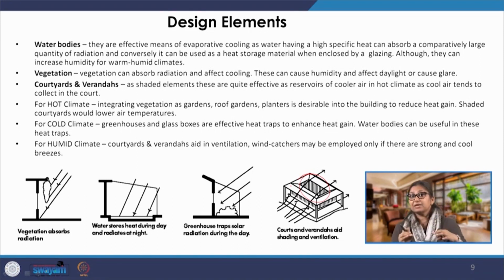That night ventilation will take away the heat, the walls and surfaces of the building will be cooled through the cool air passing through, and we have to allow cross ventilation, and courtyards allow that. So, what type of design element is required?